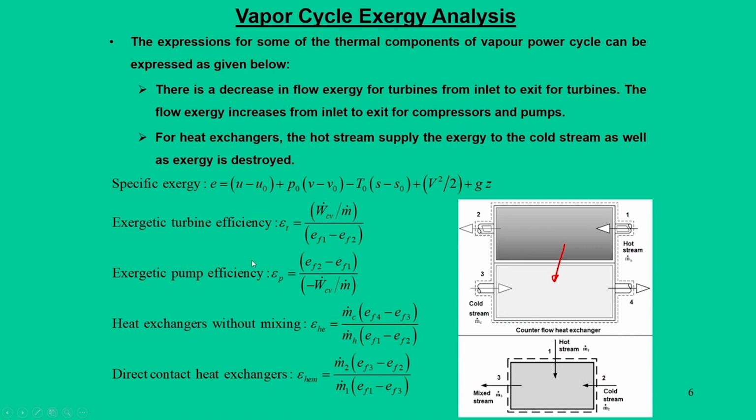For pumps the expression is completely reversed, because pumps require work as an input. For heat exchangers, the expressions are defined through the heat carried by the working fluid of the hot stream and the heat rejected to the cold stream. Here the expressions change slightly based on the mass balance. So, these are the working formulas for exergy analysis, and in our subsequent discussions we will see how these formulas can be used to solve some problems.